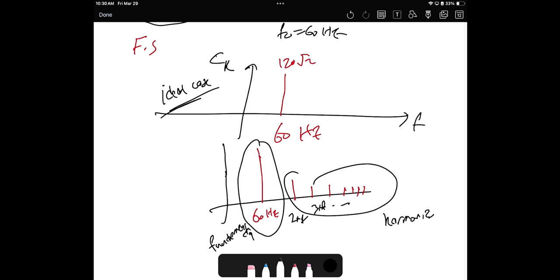So how can we make sure to get this frequency? Basically, we can use some filters. Some passive filters, active filters, low pass, band pass, whatever. There are different types, first order, second order, third order filters.